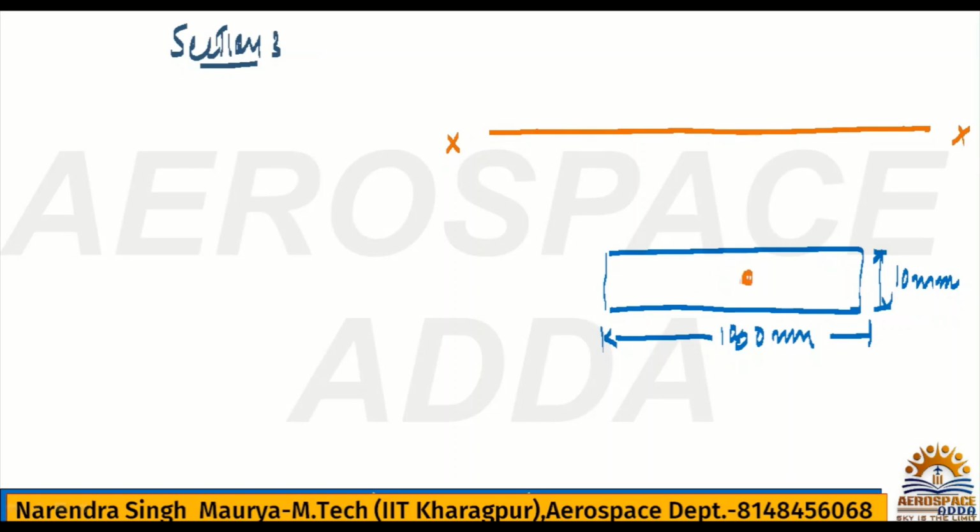This is the CG3. This is nothing but y3. And obviously we are going below the x-x axis, so this y3 will be negative. Always remember, because the x-x axis is a reference. If you are going in the upward direction from the reference axis, it will be positive, and if going downward, then it is negative. But don't worry, this is a square value only, so nothing to worry about plus and minus.